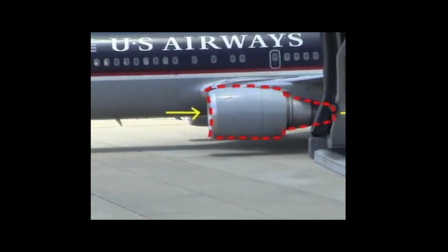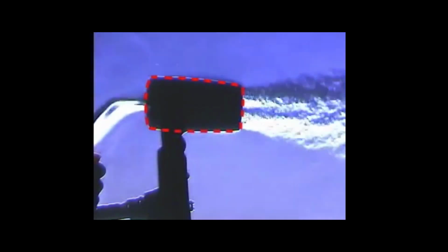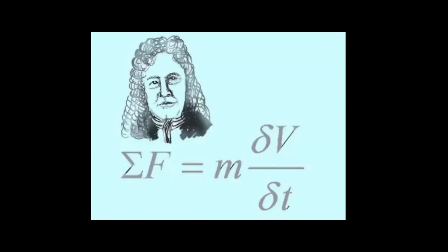Likewise, an appropriate Eulerian control volume for this hairdryer is fixed to the dryer itself rather than to the air passing through it. In this simple example, the control volume has one inlet and one outlet, and its lateral sides are impermeable to the air. Electrical energy enters the control volume, however, in order to heat the air and drive the blower that moves it.